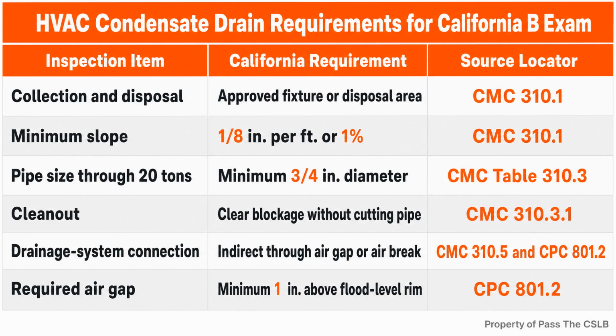The drain also needs an accessible cleanout that allows a blockage to be cleared without cutting the pipe. This is a serviceability requirement, not a decorative fitting. Once drywall, insulation, or equipment platforms surround the installation, a technician should not have to cut and rebuild the drain merely to clear ordinary blockage.